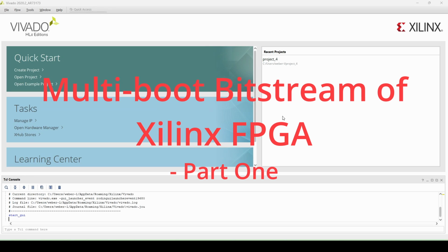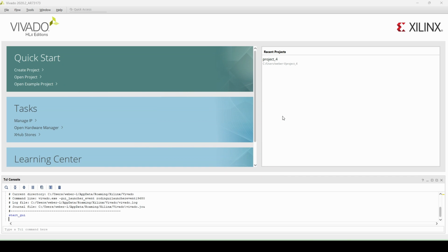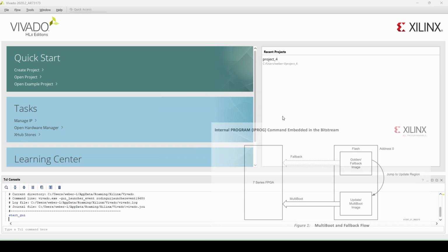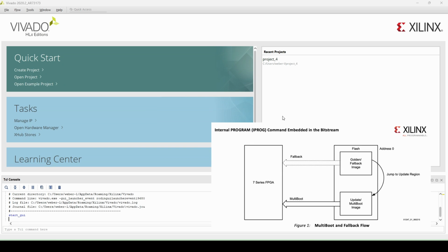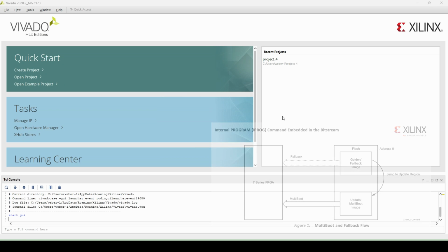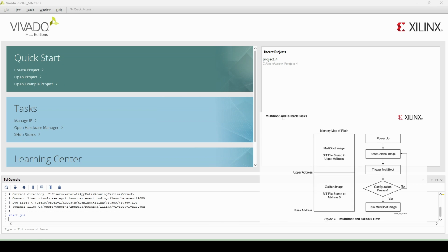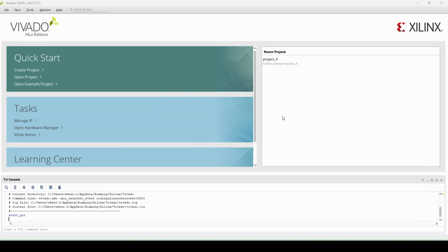Hello everyone. In this video, I will show you how to design a multi-image boot bitstream with Xilinx FPGA. For various reasons, you may need to save multiple bitstreams in the FPGA boot flash memory, for example, in-field upgrade, or call out different FPGA functions based on some conditions, etc. Then you select one of the bitstreams to be active and boot into it.